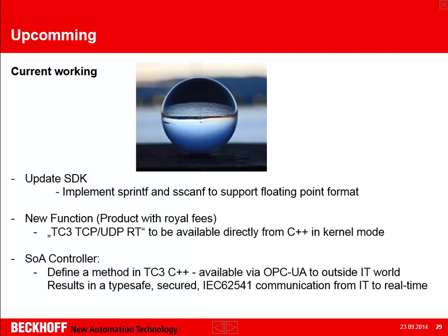The temporary name today is TwinCAT 3 TCP UDP RT, which means out of the C++, out of the kernel mode, you can open a TCP or UDP port and then communicate to your TCP or UDP partners in the network. Be aware, it's not a fully blown TCP stack, so it's a very small, limited subset of that. But of course, it's much faster than first giving data with ADS calls to the user mode and then making use of WinSockets to call to the outside world.